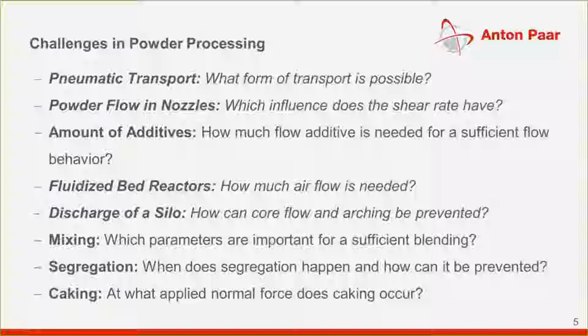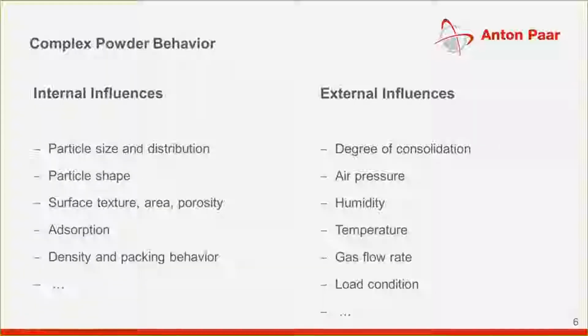This is a bit counterintuitive because we don't really see air being forced through a powder. But when the powder is in free fall, it actually fluidizes by itself during this discharge process and can also impact the powder behavior, either during the discharge or afterwards. So with this, let's have a look at powder behavior.